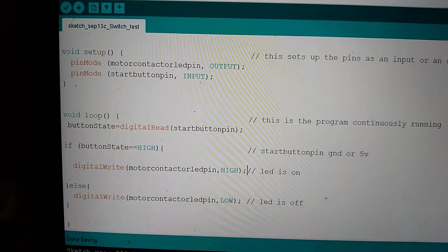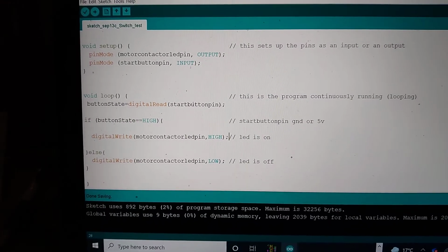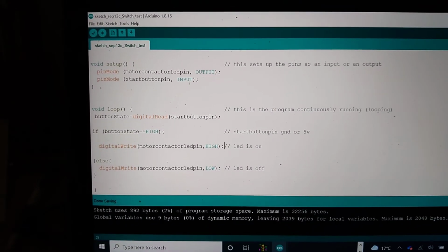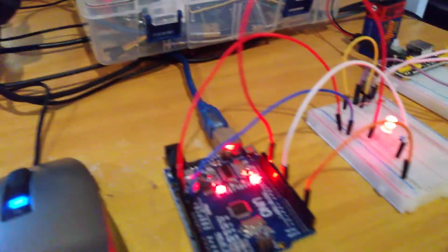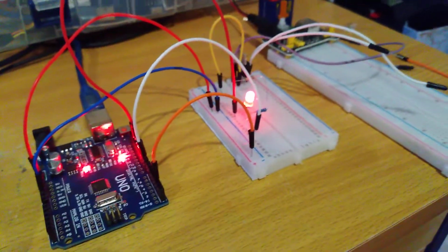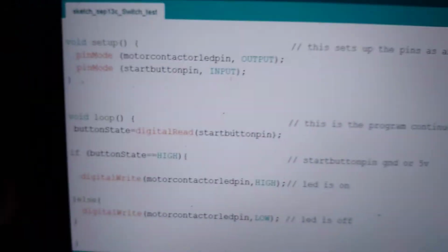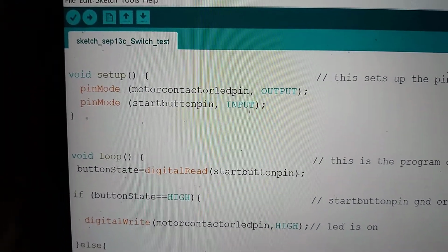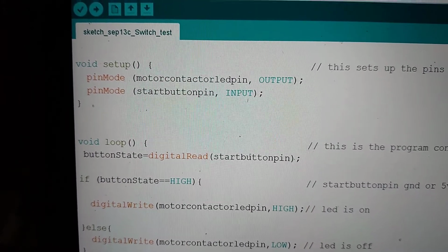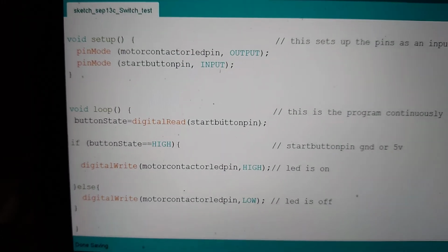The Arduino IDE. You'll see now if you've made a mistake. So when you go to upload the sketch to the Arduino, it will come up with an error and it will tell you where your problems are. What you often find is most of the problems are something fairly basic, like forgetting to put your semicolons at the end of an instruction, or having a lowercase instead of an uppercase.